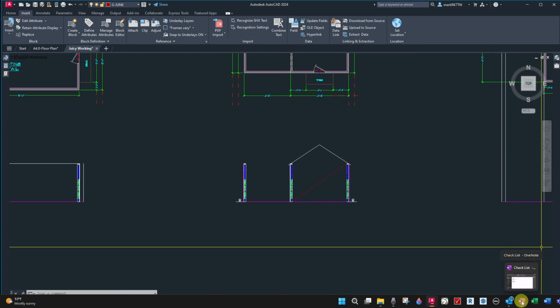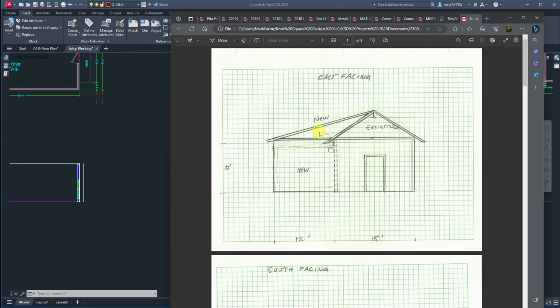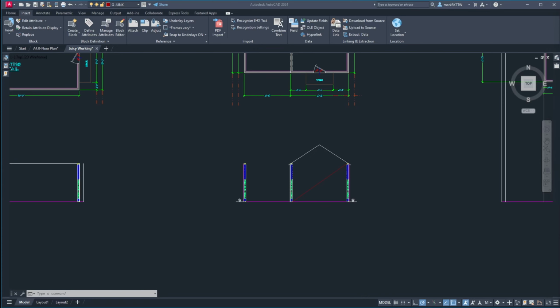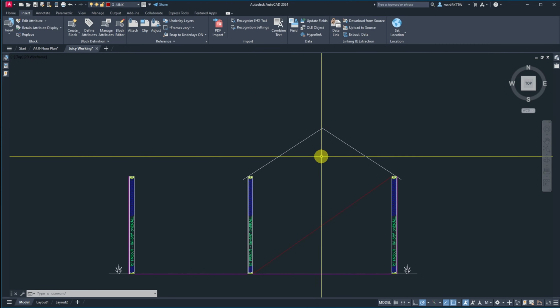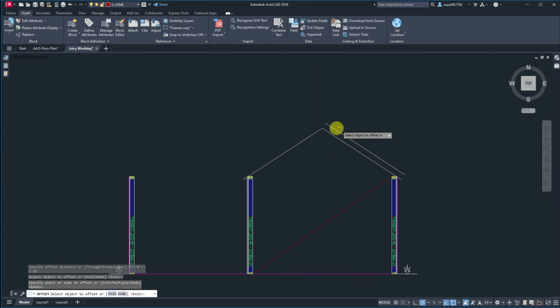I can always look at what they have provided as far as elevation goes. Not much. So it really is going to be kind of a guessing game. So with that being only 15 feet, I'm going to just make a guess from older construction. The oldest date I could find this in what's called Montana Cadastral was 2002. So this could be as small as probably a 2x8. So let's offset 7.25. And let's just put that member in there.